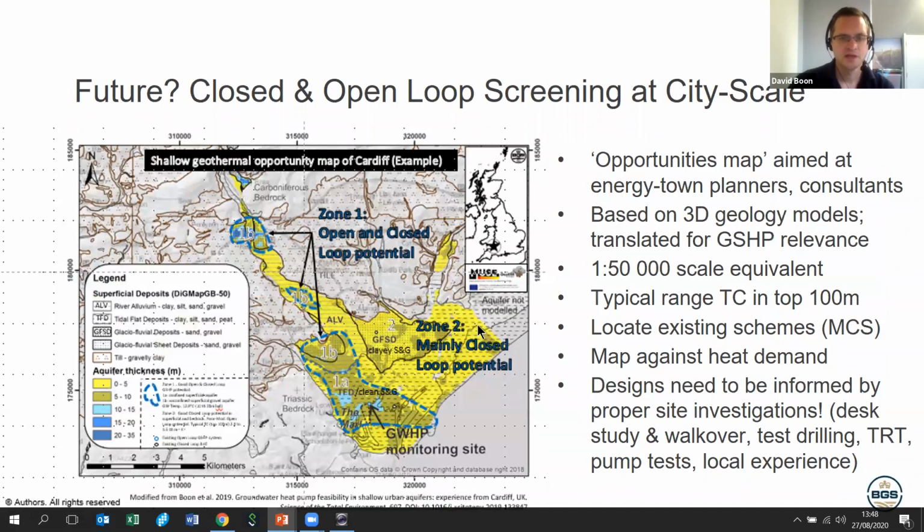And I wanted to touch on urban ground source heating. I think that's going to be a really big thing in the future. District heating systems, 4th and 5th generation district heating, using either central heat pump centers or individual heat pumps in homes and ultra low temperature water distribution systems, is getting interesting in the UK now. And it's been done for years in the Nordic countries and Germany and Holland really well. So we're really starting to pick up on these types of projects in the UK.